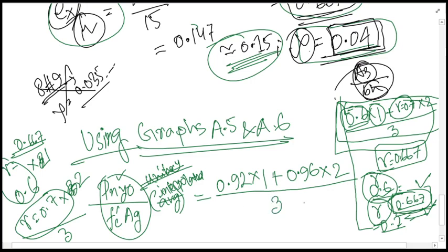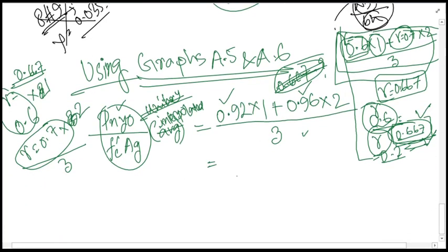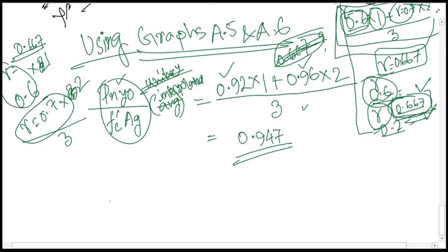It is not necessary that you apply this method. You can differently obtain this value for 0.6 and this value for 0.7, and from that you can also calculate the value for 0.667. It will give the same value as when I applied this formula. You can try it on your own, and from there we have obtained the value as 0.947, and from this we can calculate the nominal strength Pny about the y-axis, which will be 0.947 multiplied by fc prime multiplied by Ag, the gross area.